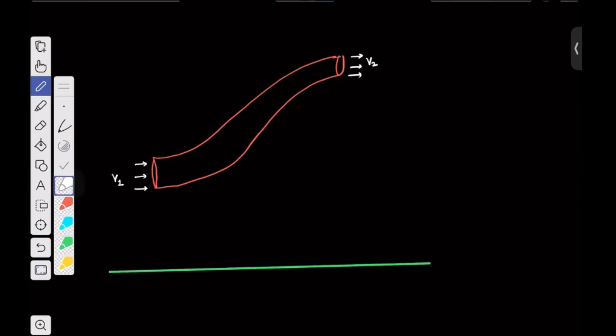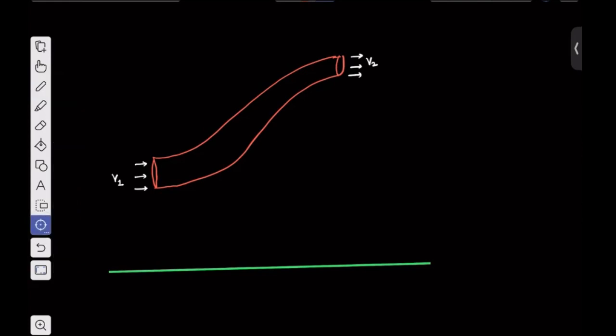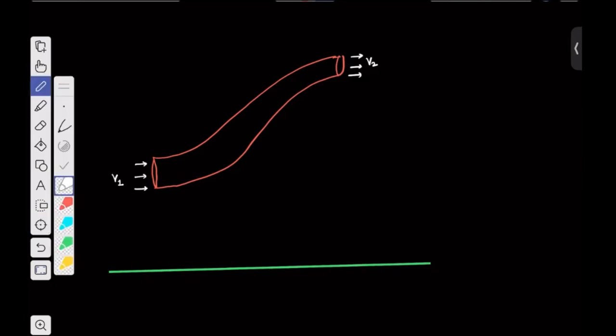So suppose in a very small time interval, what we want to figure out is the net work done by the surrounding here. And since here we are not talking about some particle, correct? Here we are talking about a system where some flow is happening. So if I consider this section of the tube as our system, then work done by the surrounding will be whatever is not in the system. So the surrounding is doing work. One is gravity doing work. Other is the pressure forces that are there at the ends. Maybe I'll name them as well: whatever pressure forces are acting at end A, and whatever pressure forces are acting at end B.